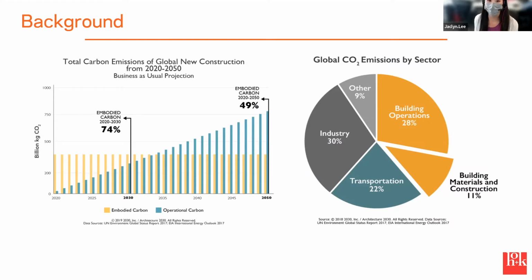Embodied carbon from buildings accounts for 11% of total global annual carbon emissions and includes the carbon emissions associated with material extraction, processing, manufacturing and construction, repair, and demolition or reuse. Most of these emissions occur before and after the use phase of a building, when operational carbon, emitted during use of HVAC, lighting and appliances, is greater. As engineers and performance designers at HOK, our goal is to reach a minimum of 50% reduction in both by 2030 and 100% reduction by 2050 at the latest, to help prevent catastrophic climate change.